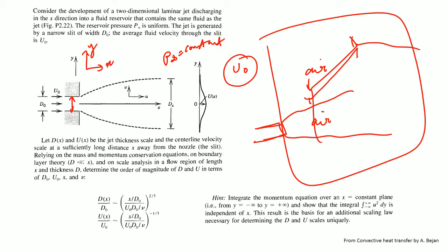Now, we have sketched something over here to give you an idea of how the flow velocity will actually look. We know that it is coming out with a velocity u naught, which is constant. As the jet spreads in the radial direction, you can imagine that the velocity should slowly drop. Here it is almost like a top hat kind of profile. So, as you go to any particular cross section, you expect this would be the kind of profile that we have drawn over here.